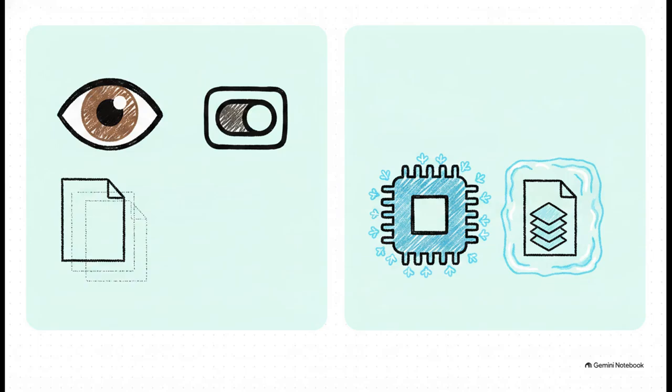Now, what's really interesting about this distinction is the subtle yet incredibly vital difference between just managing visibility and actually managing system performance. As your drawing gets complex, you have two main tools. We have on/off. This simply shows or hides the layer from your screen. It just gets it out of your visual way. But then we have freeze/thaw. Freezing a layer doesn't just hide it, it temporarily disables that layer entirely from the software's memory processing. So if you are working on a massive project and your computer is suddenly lagging, freezing the layers you aren't currently using will massively improve your system's performance.